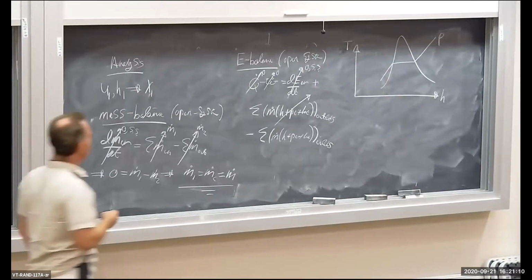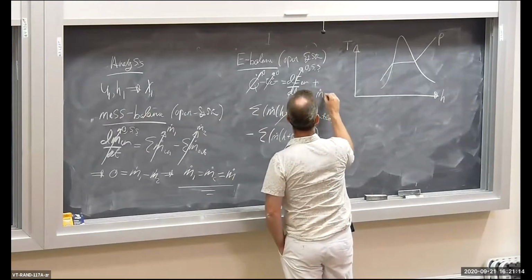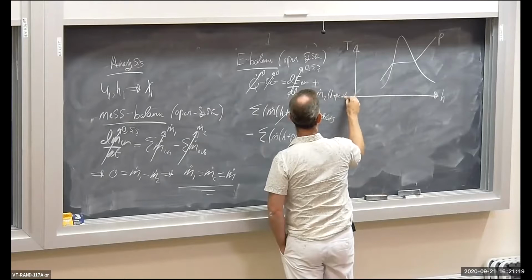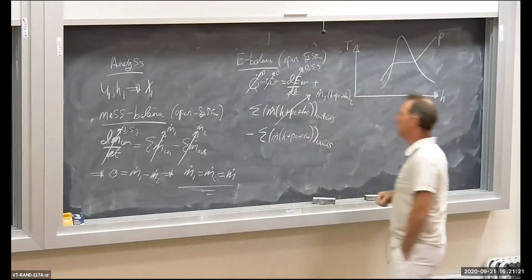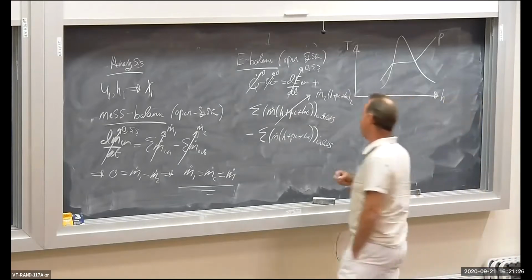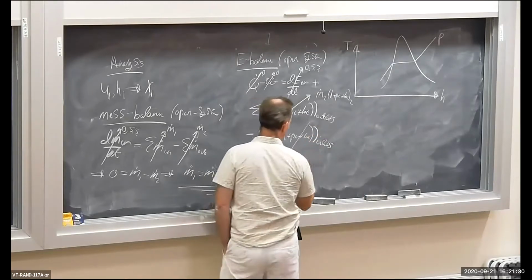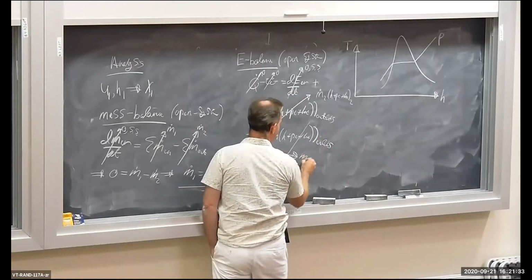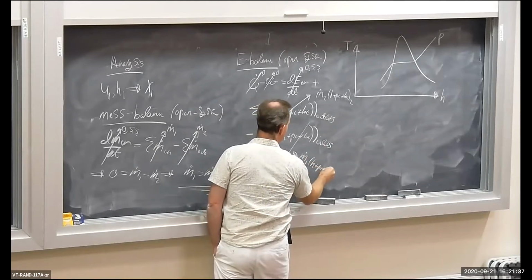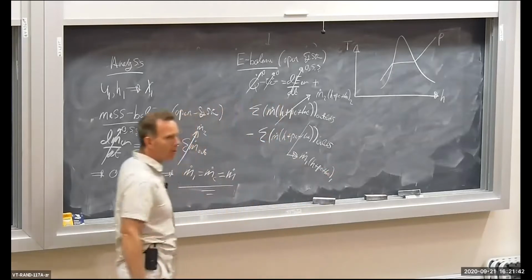So the summations go away, and the outlet term becomes m dot 2 h plus PE plus KE at the outlet. One outlet, and that's at location 2, so m dot h PE KE at 2. At the inlet, we have one inlet, so the summation goes away, and I get m dot 1 h plus PE plus KE at the inlet, which is at location 1.